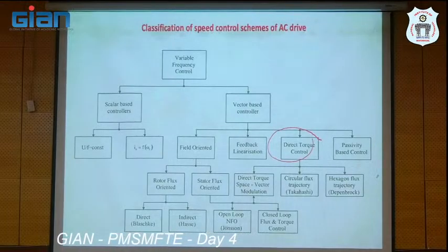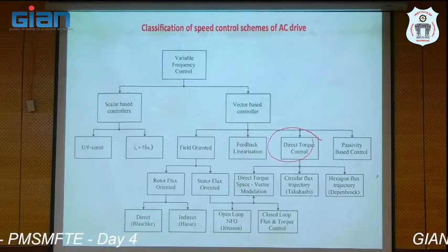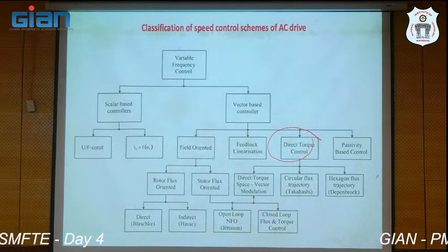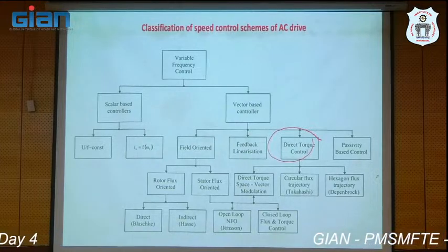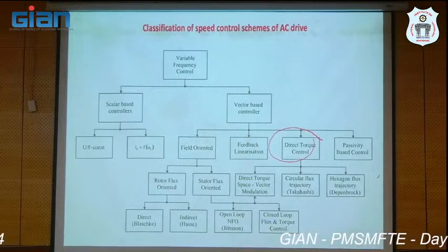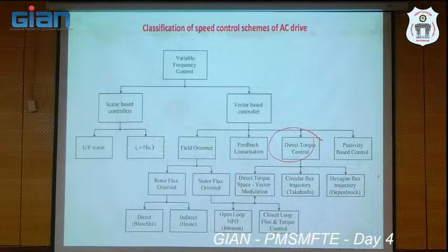We need to minimize the order of the torque expression, or improve the torque profile of the AC machine from 7th order to 1st order; that is why we adopt the field orientation method. But if the rotor flux position is not estimated accurately, then your algorithm will not work well. Then the torque response will not improve to be the same as a DC machine.